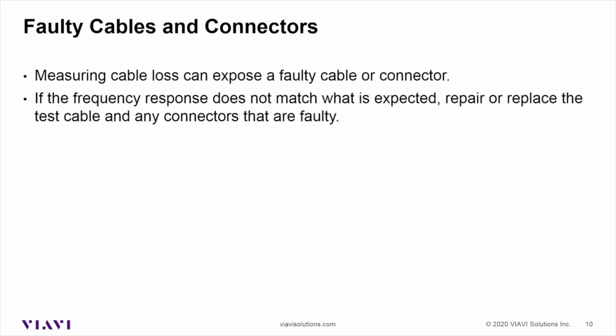We talked about it a little bit. And I said, well, let's characterize this cable, see what our cable loss is. And they hooked it up, and they didn't get any signal into the service monitor, nothing we were seeing. And ultimately, of course, we figured out that the cable was bad. Turned out one of the connectors was actually missing the center pin. So that sort of thing can happen, and that's not something that a calculator can tell you, okay?